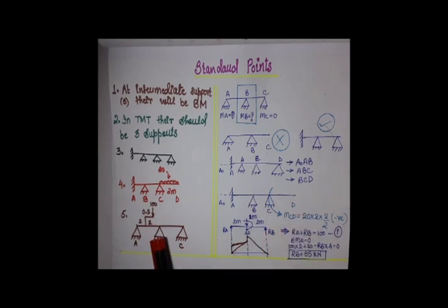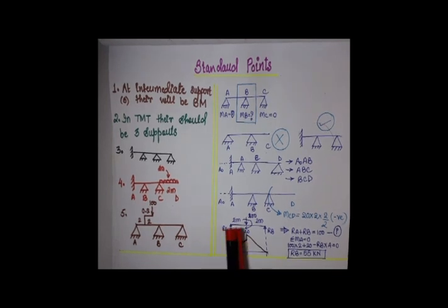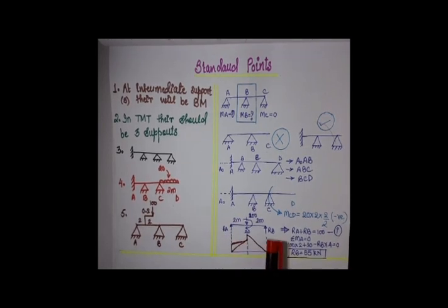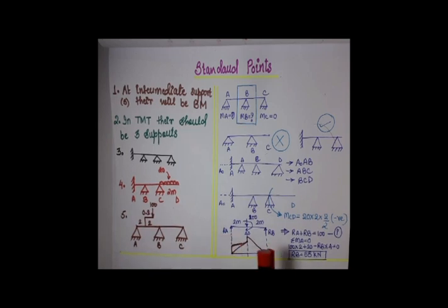Moving to the next, last and the most important point, here the beam is ABC. Now this is a complicated moment given on the beam. So how can it be solved? Let's see that. Here first we need to simplify it. Now this is a beam, and 2 supports would be acting, that is RA and RB. Why RA and RB and not RC? Because the moment or the force is acting between A and B. Therefore we take the reactions RA and RB.